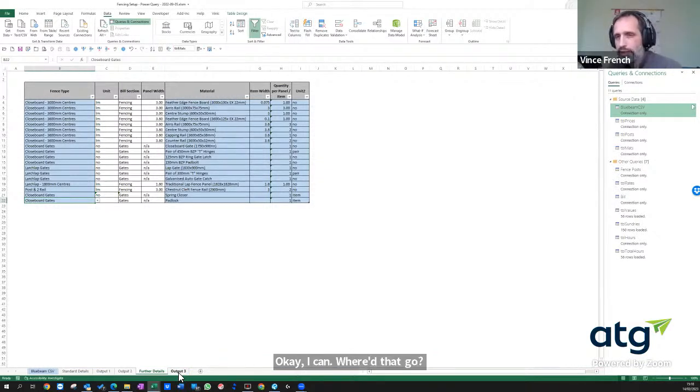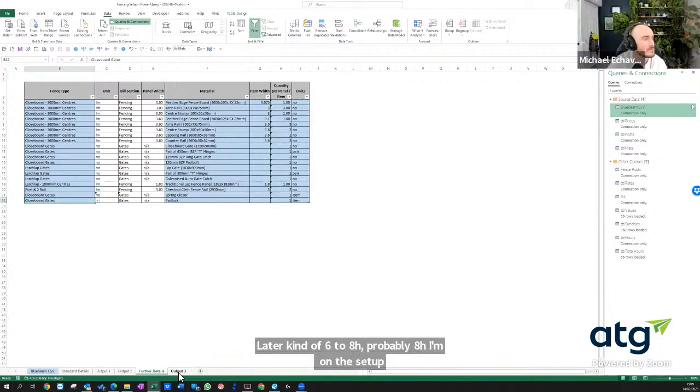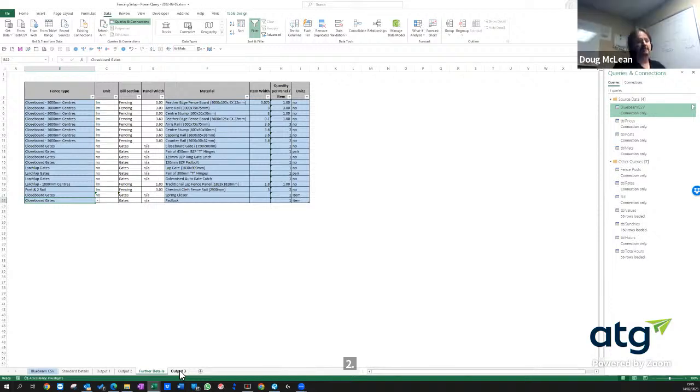Like I've done a setup for measuring the sewers on a housing site, and with Revu you get a very clear markup, and you can show exactly what's been measured. With a few custom lines you can quite clearly show different types of pipe work that have been measured. It's all there. I did a quick measure on a job for someone just before Christmas, and I asked how long it would normally take them because they didn't have the time. They said kind of 6 to 8 hours, probably 8 hours. And on the setup that I've got, it took 2. Yeah. Wow.